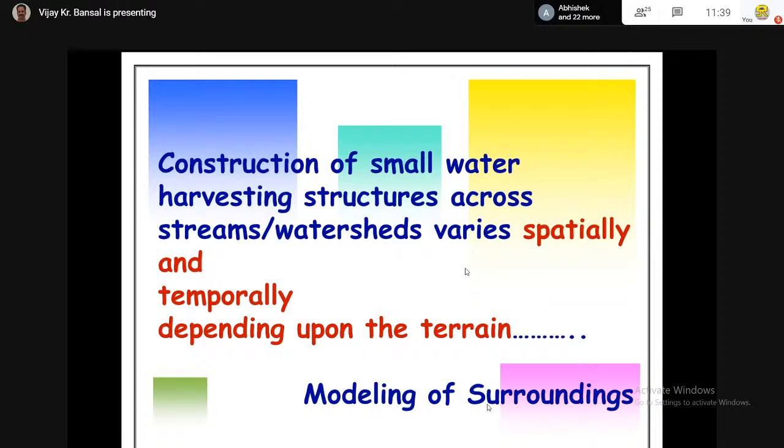Control along the line, specify location. For road planning, if you click a point, the line joining the points shows from where it is visible and which portion is not visible, just like here. If you move toward this side, this is a hilltop actually. So which portion is visible, which portion is not visible: that is visibility analysis. Then runoff analysis: let's say this is a water tank location, and because of an accident this tank bursts, from where that water will go outside, that is one direction. Sunlight visualization also,